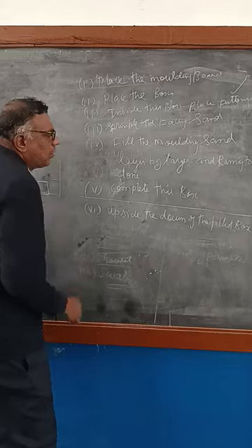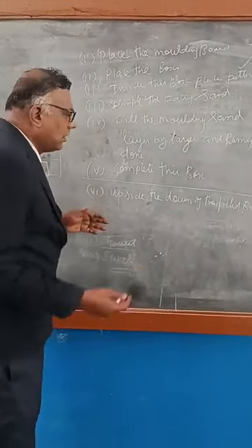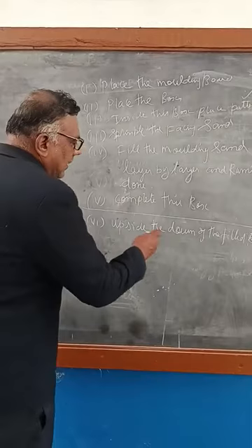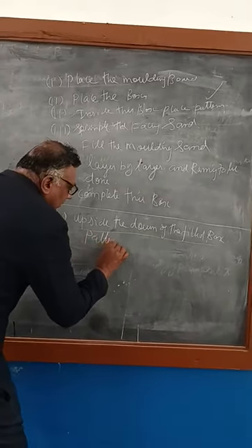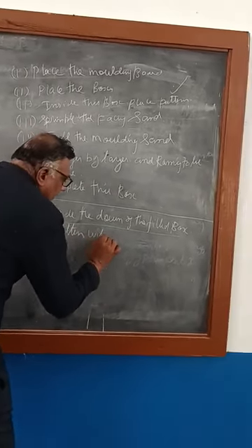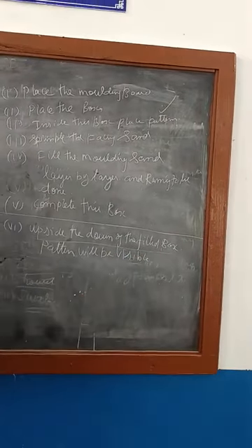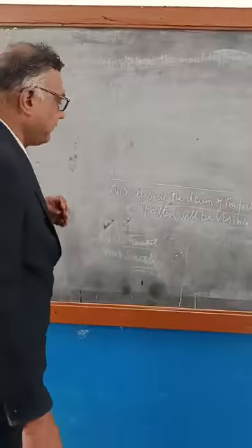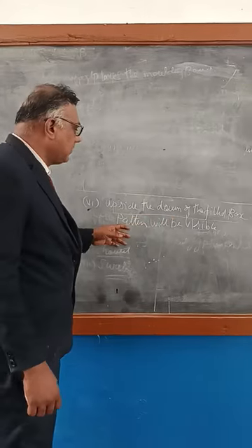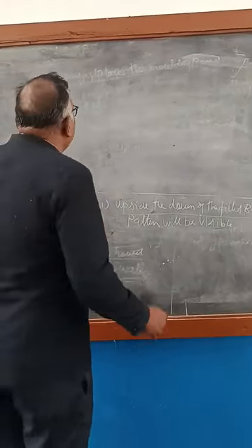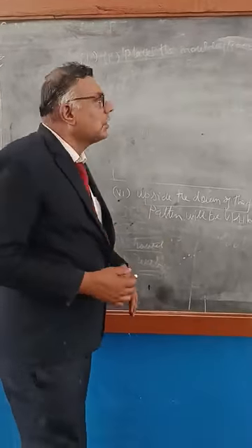Right. So while ramming layer by layer, the pattern will be done. Now if you keep the filled box upside down, the pattern will be visible. So, upside down, the filled box, the pattern will be visible. So next, before placing the other box, use parting sand.